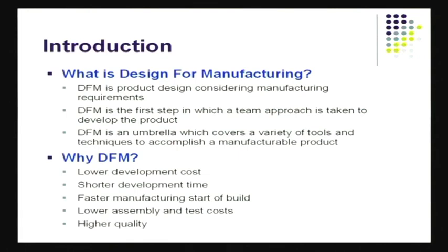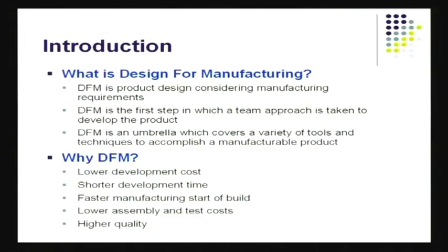What exactly is design for manufacturing? If you look at a product, almost any product, ultimately, you've got to remember that it's got to be manufactured through some manufacturing system. If it is designed in a way that is not conducive to easy manufacturing, the cost is going to be high, perhaps the quality will be affected, perhaps the handling would be affected, and so on and so forth. So we've got to make sure that the design itself keeps this mission in mind, that eventually I've got to produce this product in a manufacturing outfit. This being the goal, certain special approaches have to be taken to make sure that you can manufacture the product that you've designed.